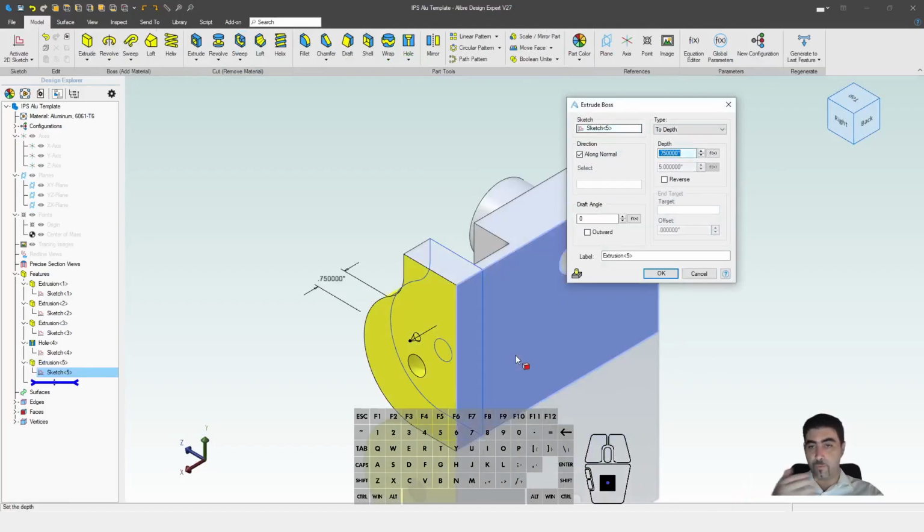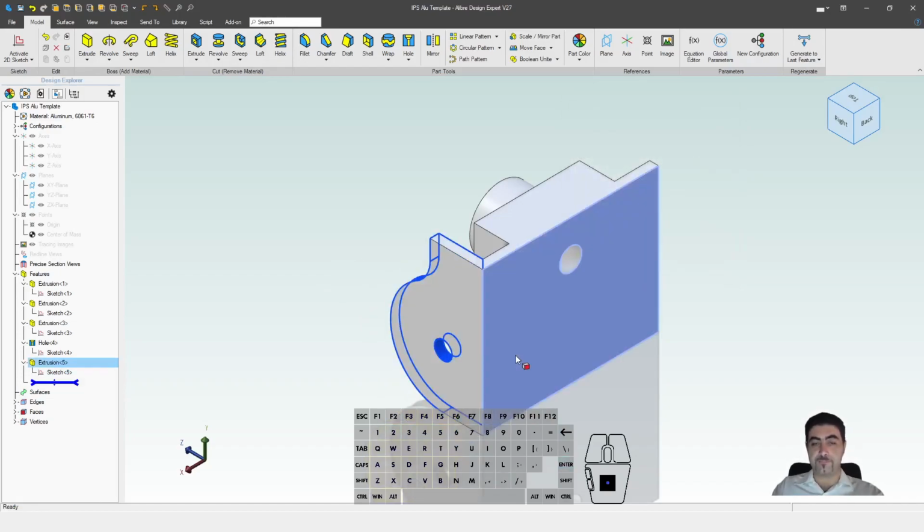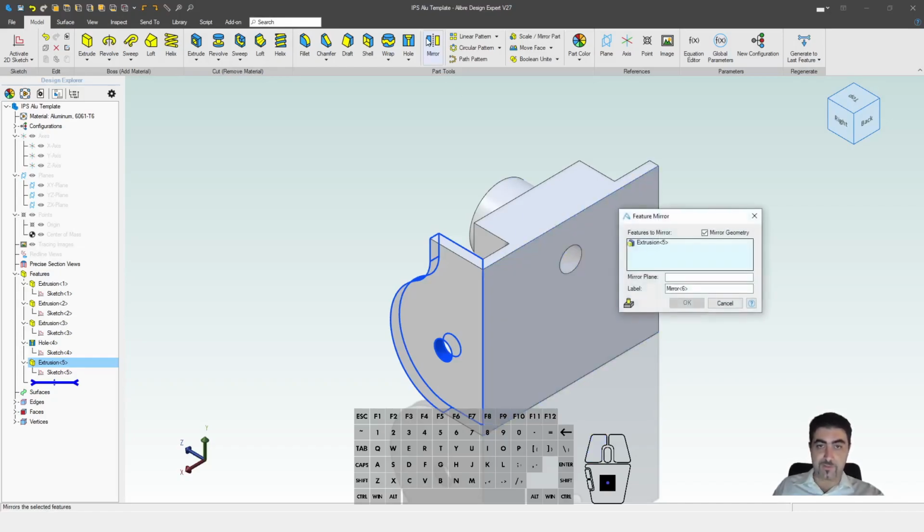E. Well, in practice, while I was practicing, I saw that this goes the opposite way that it should have. So minus, right, when we put minus dot 2, 5, enter. Right, and straight to the mirror plane, straight to the YZ plane, right? Y, Z, you can see it down here. Straight to the YZ plane.